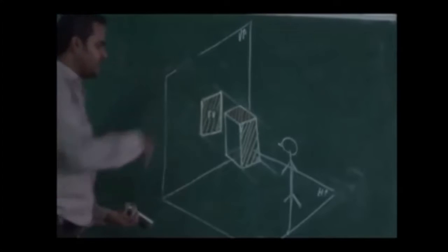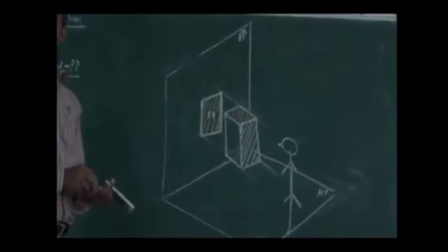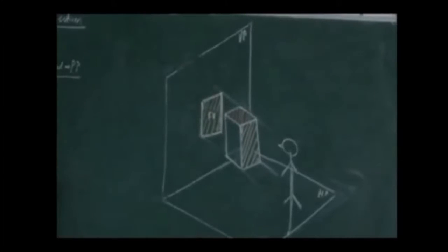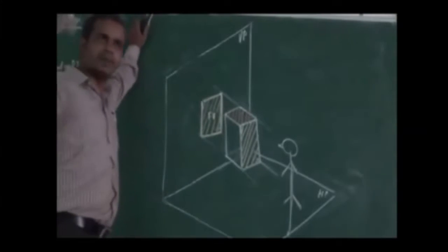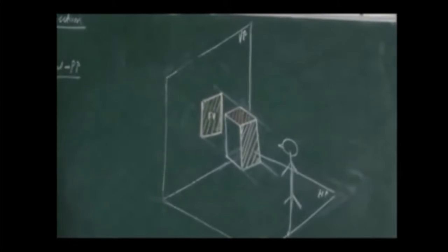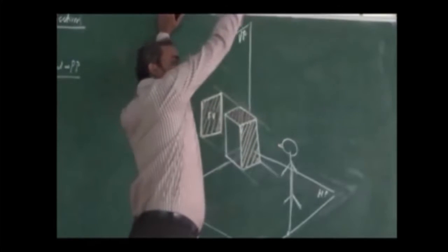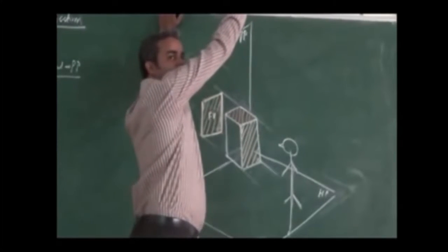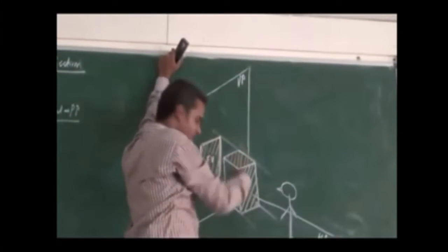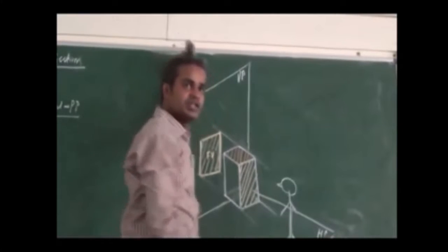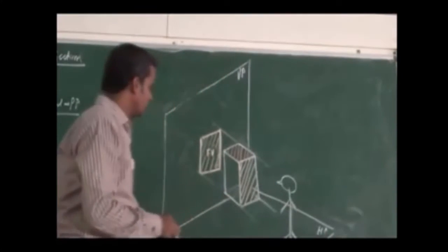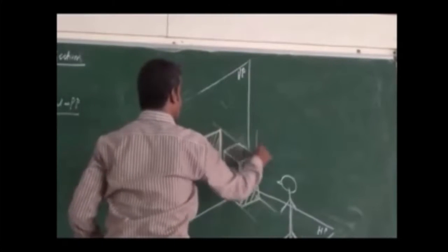this face will be seen in the horizontal plane. The observer I have to keep without violating this setup, to obtain another view, so I am going to obtain a top view. Without violating this setup, for this the observer has to look at the object from the top. So the observer will be sitting there, it is the first one, then the object is there, then I have a horizontal plane at the bottom. The setup is not violated, and I will be performing an orthographic projection from the top.